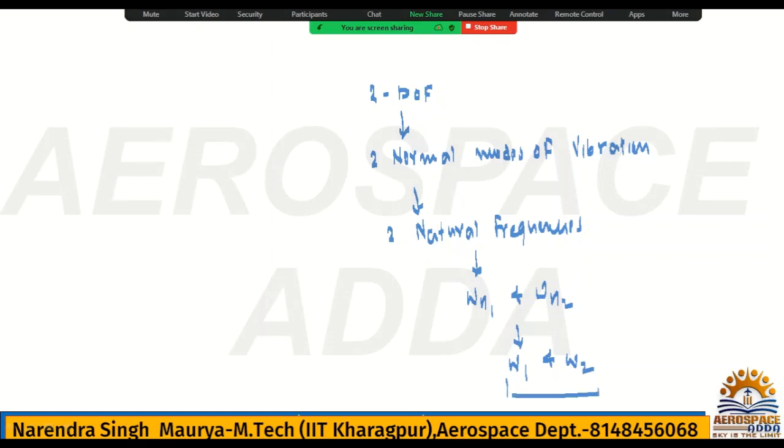So in the case of the first degree of freedom, we calculated one natural frequency. Now we will have 2 natural frequencies. Why? Because it's a 2 degree of freedom system. We require two independent coordinates here, x1 and x2, and for that we will have 2 natural frequencies.